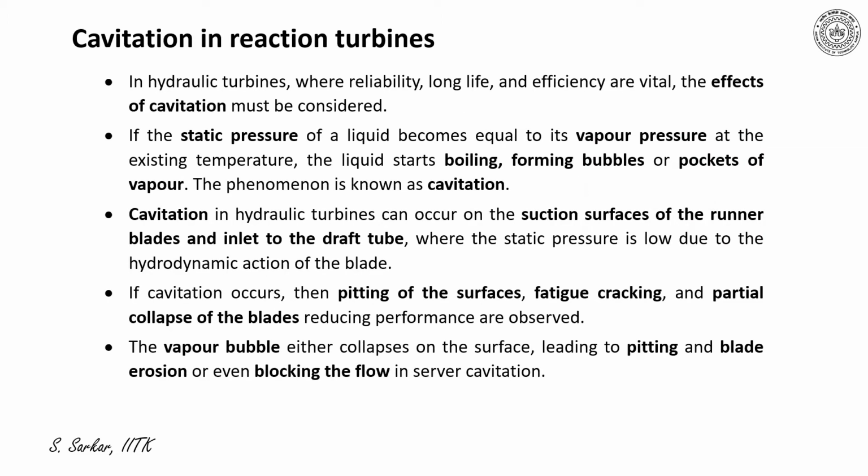Further, I'd like to add that in hydraulic turbines where reliability, long life, and efficiency are vital, the effects of cavitation must be considered. If the static pressure of a liquid becomes equal to its vapor pressure at the existing temperature, the liquid starts boiling, forming bubbles or pockets of vapor. This phenomenon is known as cavitation.